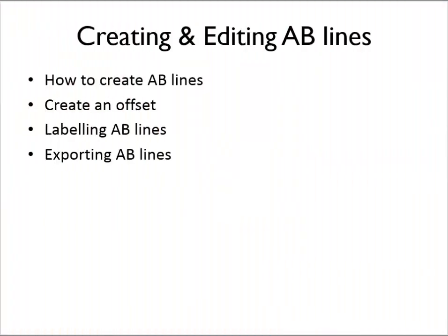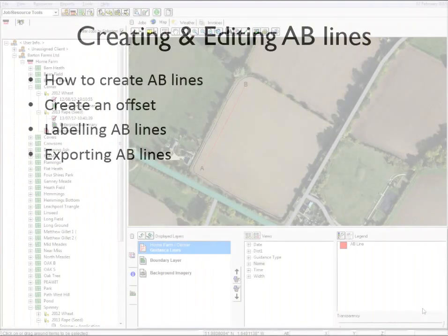Hello, in this video we're going to be looking at creating and editing A/B lines. We're going to look at how we create A/B lines in the software, create an offset, how to label A/B lines, and then how to export them to a monitor.